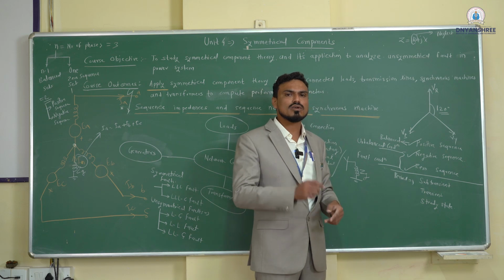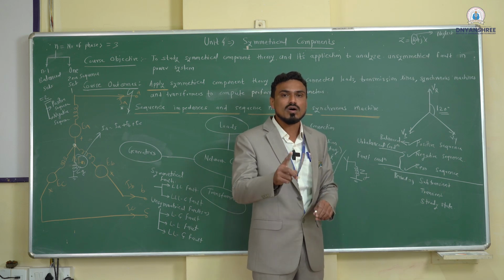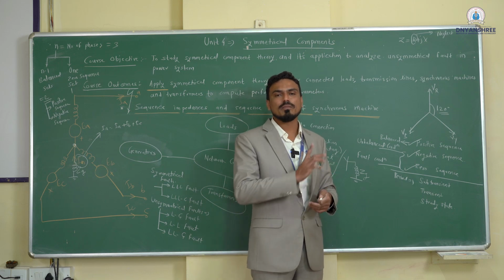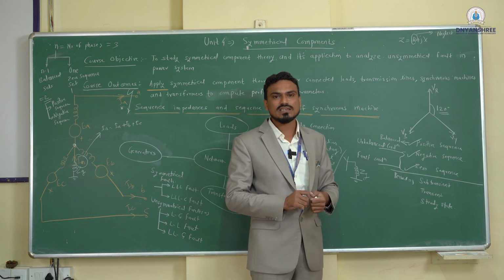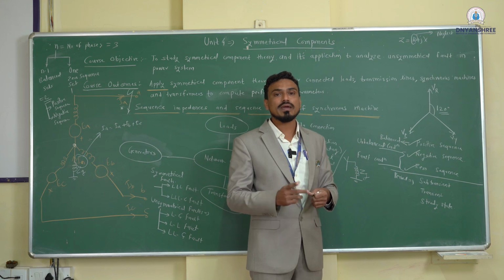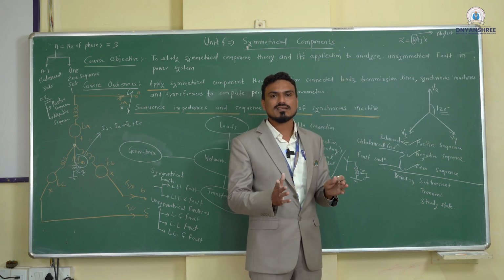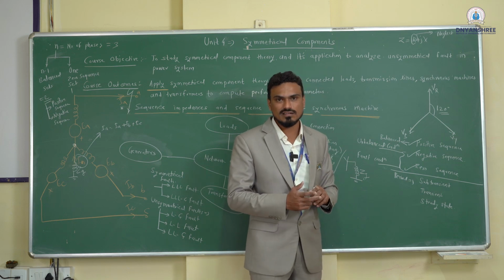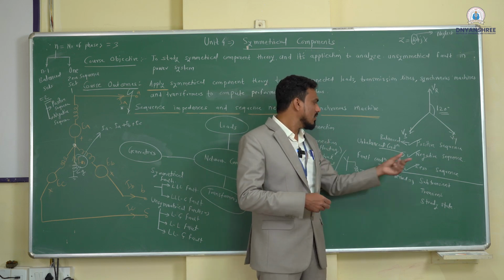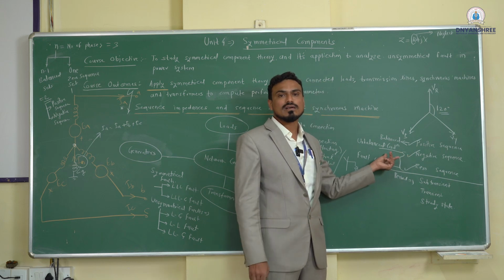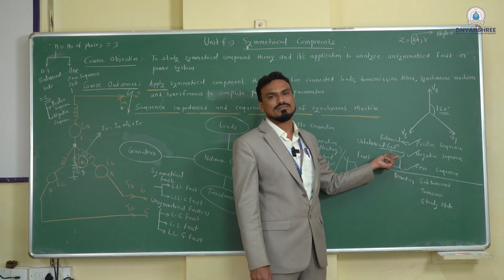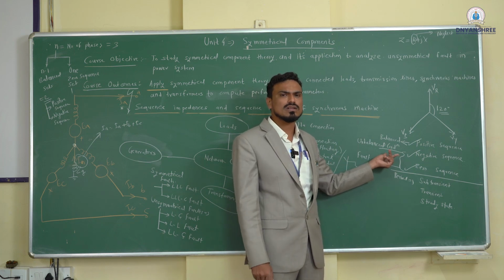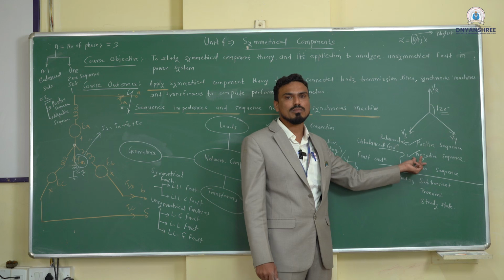If the negative sequence component is present in the network, it causes heating of the equipment. You may experience some warmness in the equipment beyond its expected limit. It also causes losses in the power system, in the network and in that component. These are the consequences of the negative sequence component.